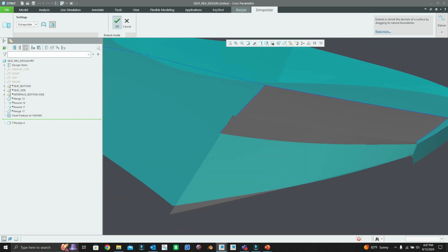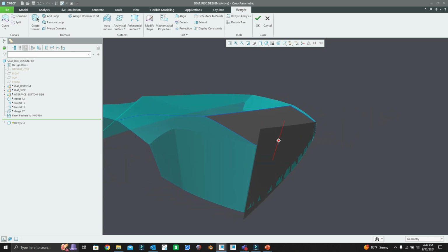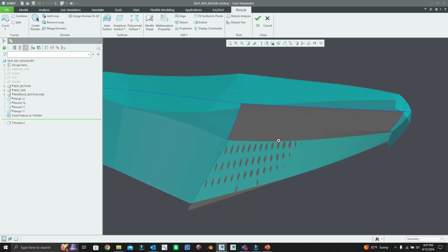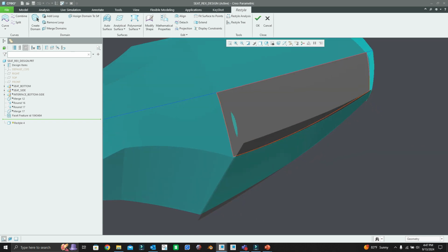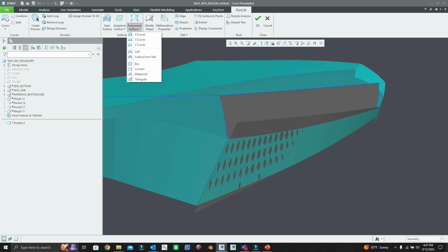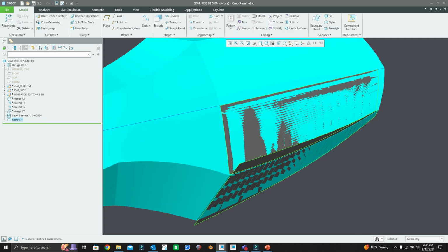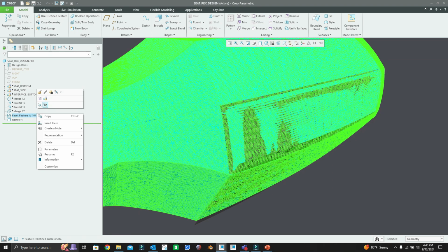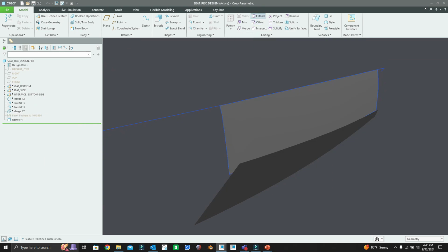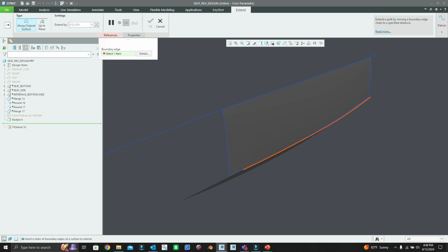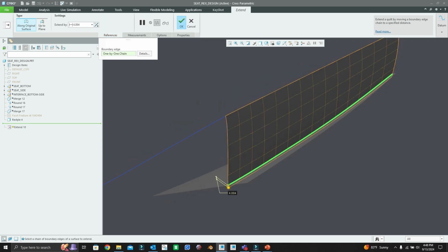And of course, we want to do that because I need to merge these surfaces together or trim them, right? So I can't extend the surface that I created using the curves, but I can extend the surface if I'm using one of the surface options below, like box, corners, and midpoints, right? So now if I click OK, I can use Creo's default extend tool up here and then select this edge, for example,